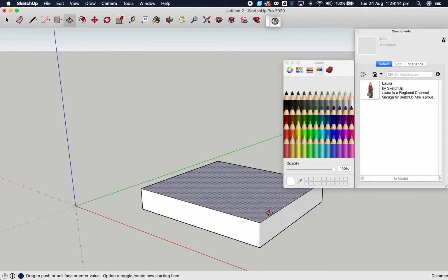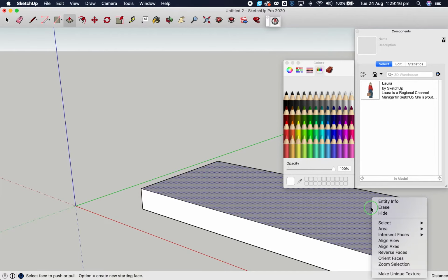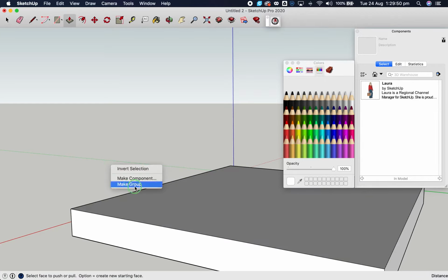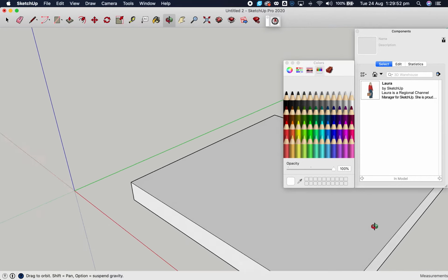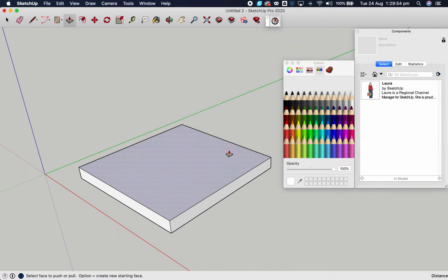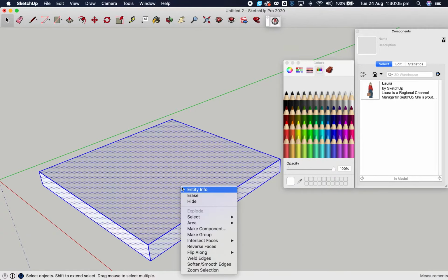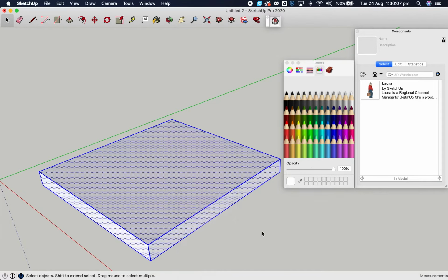300mm slab, for example. I might make it a little bit bigger. Whoops. I've been using other 3D programs lately, so I'm a bit sort of sketchy at times. Okay, so here's my slab. So the best practice is anytime you create a level of something, you need to triple click on it and then group it. Okay, so then at any stage you can deconstruct your structure.